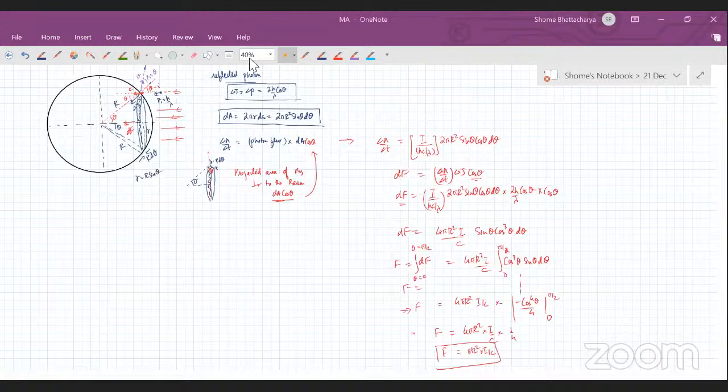So its thickness is not r dθ then. Its thickness becomes r dθ's vertical projection. When you work out the angle with the vertical, it will be θ. So the thickness of the ring projected on the vertical plane, to which the beam is perpendicular, is actually r dθ cos θ. So that's why the projected area becomes dA into cos θ.